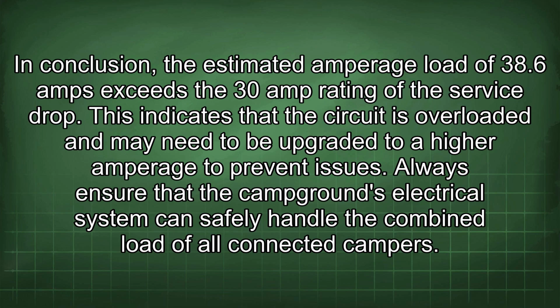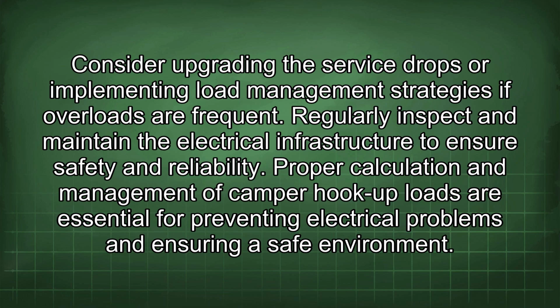Always ensure that the campground's electrical system can safely handle the combined load of all connected campers. Consider upgrading the service drops or implementing load management strategies if overloads are frequent. Regularly inspect and maintain the electrical infrastructure to ensure safety and reliability. Proper calculation and management of camper hookup loads are essential for preventing electrical problems and ensuring a safe environment.